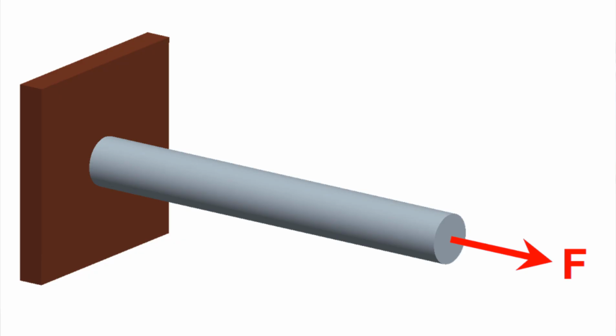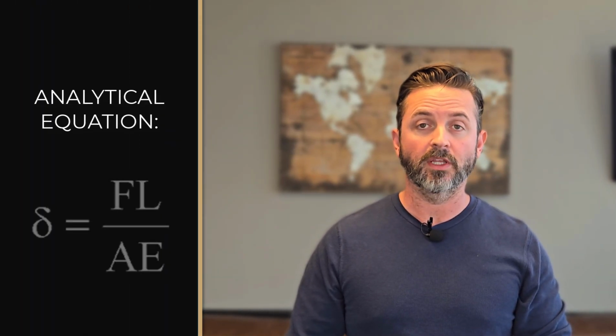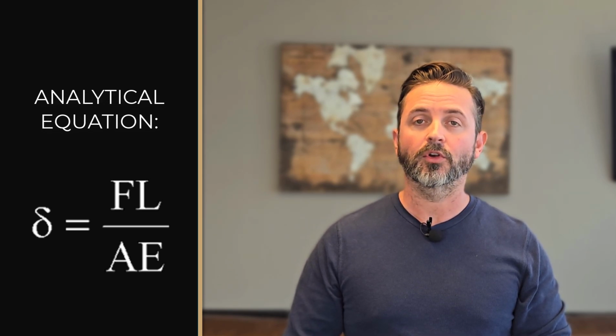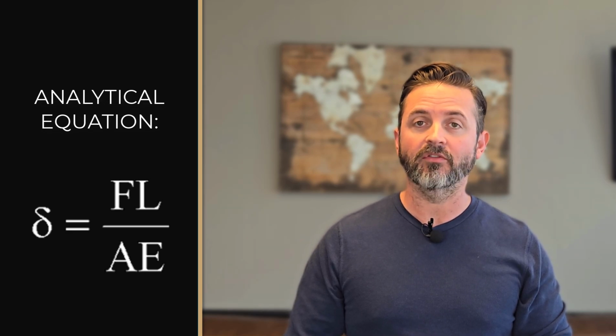Let's take this simple bar problem as an example. We have a round steel bar attached to a wall with an axial force applied on the end. There are closed-form analytical equations that provide for the deflection at the end of this bar related to the applied force, F, the length of the bar, L, the cross-sectional area of the bar, A, and the modulus of elasticity of the material of the bar, in this case steel.